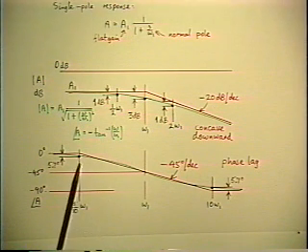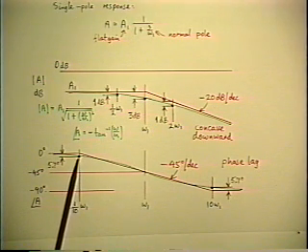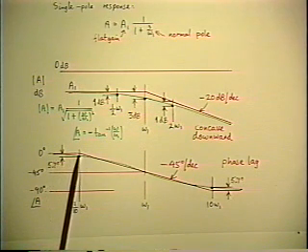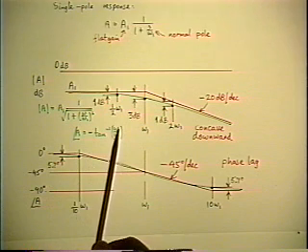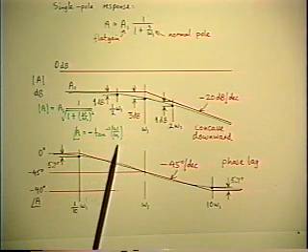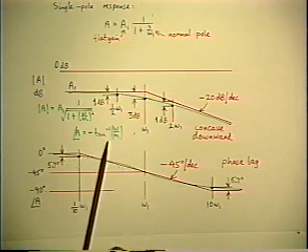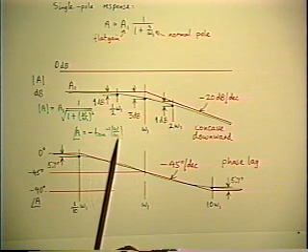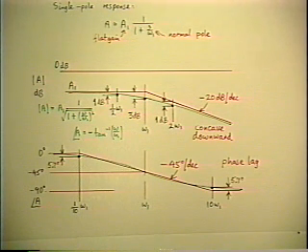The maximum deviation actually occurs at the asymptote intersection. And it's easy to evaluate that, because if you put in the formula omega equals 0.1 omega 1, which is where that asymptote intersection is, arctangent of 0.1, remember some high school trigonometry? Series expansion of the arctangent function.